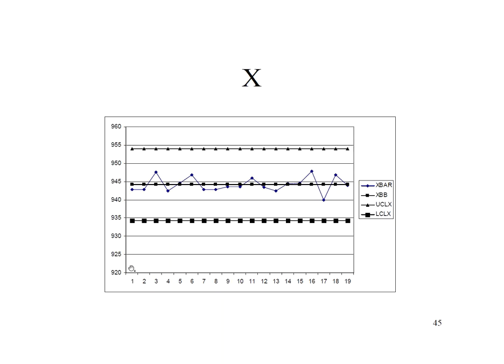So this point here, X bar, is the average oxide thickness on a particular wafer. And then the next wafer, and this assumes independent runs where you're processing one wafer per run. All right, then this line in here with these squares is the grand mean, and it's the mean of all the samples, all right? And so depending on how you vary around the mean, you can make decisions about whether your process needs to be improved or to let it go.